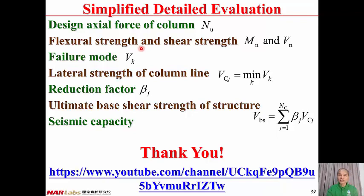Then we consider all possible failure modes. From each failure mode, we can have the lateral strength of the column line, and from the lateral strength under all failure modes, we pick up the minimum one.